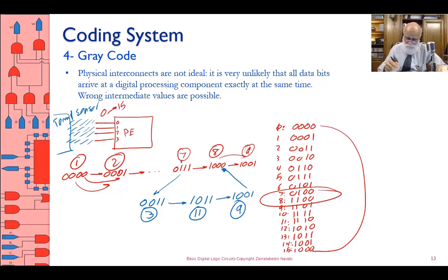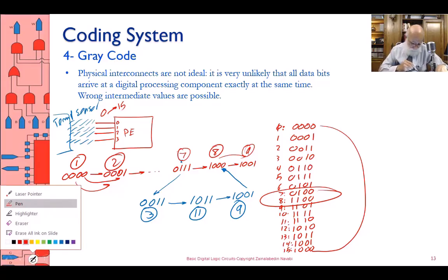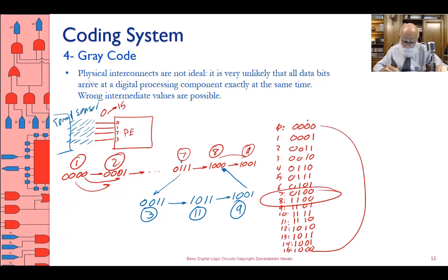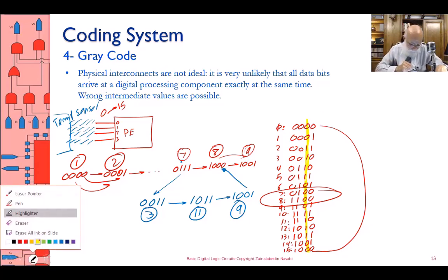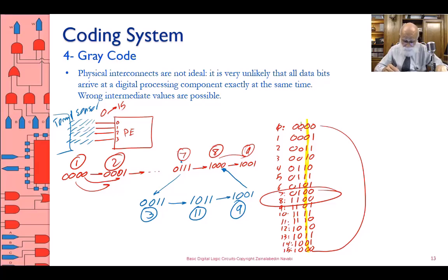If you want to remember this, look at the first column. The first column has a 0 and then 2 1s, 2 zeros, 2 1s, 2 zeros, and so on. The second column, do this. The second column, instead of 2 zeros, has 4 1s, 4 zeros, 4 1s, 4 zeros. Now, if you have 5-bit gray code, then you can just write those down too. Third column, you start with, instead of 2 zeros, you start with 4 zeros, then 8 1s, 8 zeros, and so on.